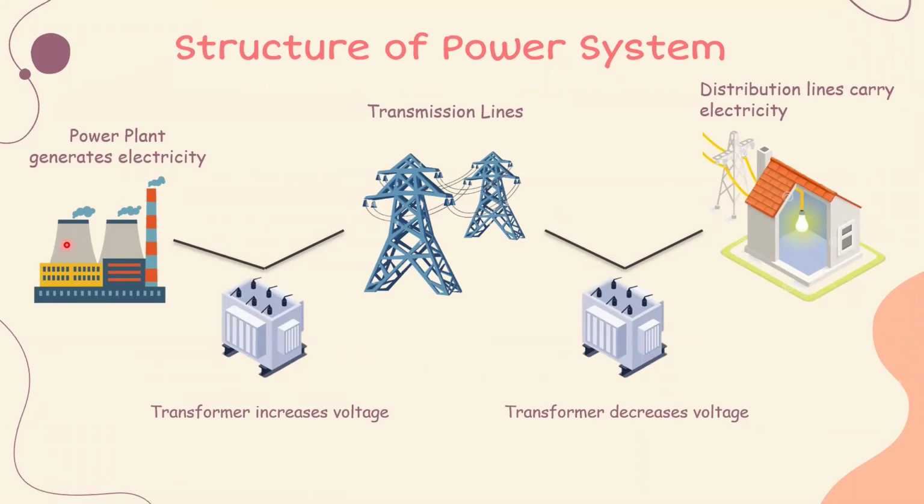So, at low voltage generation, we can construct a smaller alternator with thinner and lighter insulation. For stepping up system voltage, we use step-up transformers and their associated protections, as well as operation management at the generating station, which we call a generation substation.